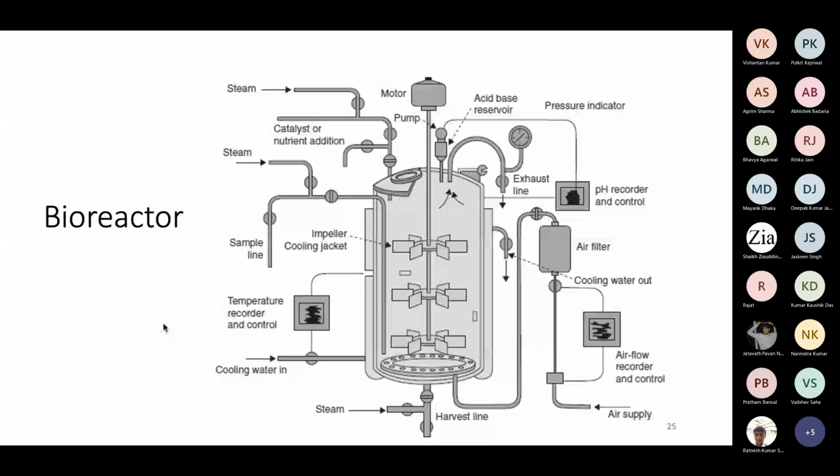So whatever weight and torque is required to maintain the shaft and the top-mounted stirrer system will essentially utilize a certain amount of energy which is actually not required, because you don't need any mixing in the headspace area. So to avoid that, for a very large diameter and tall reactor, you can mount the motor at the bottom of the reactor.